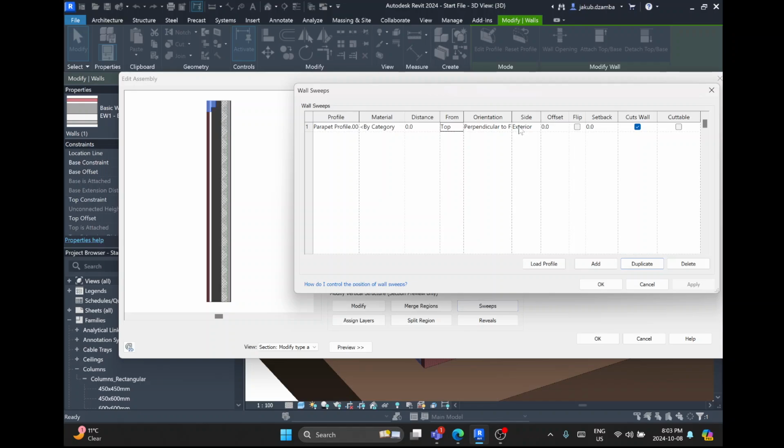So I'm going to go from the side it's inserted. There are a couple of ways to do this, but this might be the easiest one. So you go from exterior to interior, apply, and it flips. And now I just need to move it from the inside face to the outside face. Now I think the wall is 748 millimeters, if I remember correctly. And I moved it in the wrong direction, so let's go minus, wrong side the interior, and we want the minus to be in here. So now let's try it.